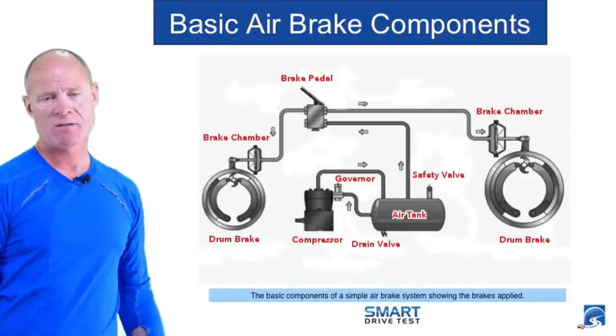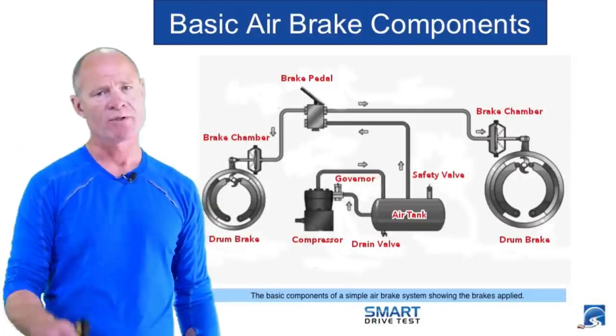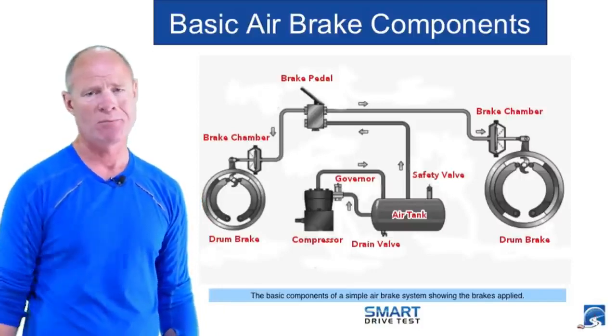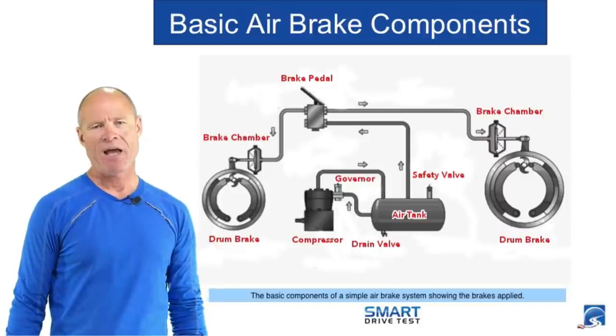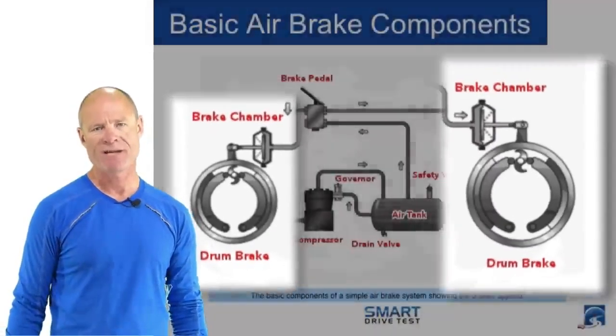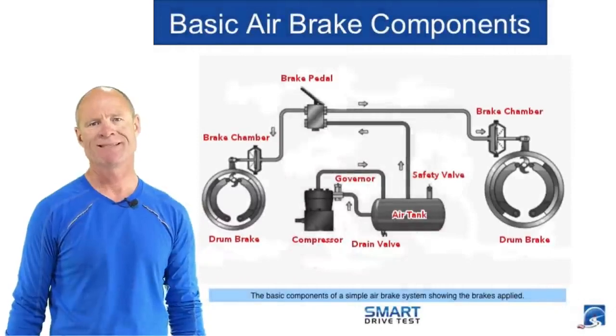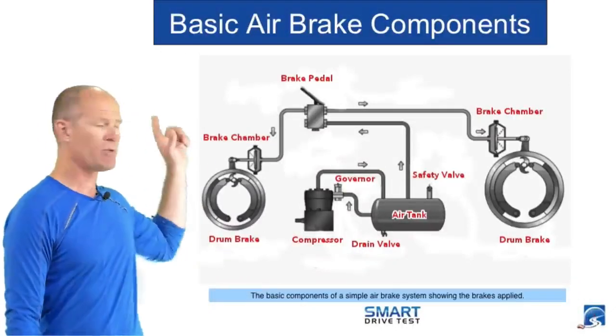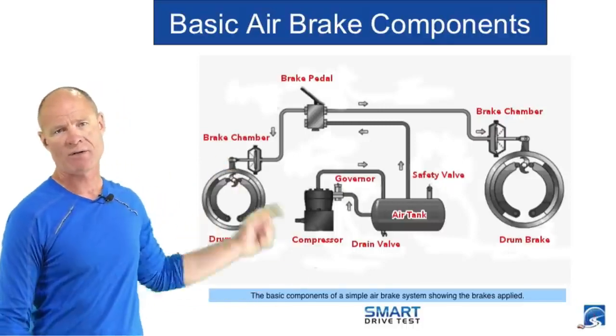The brake pedal can also be called the foot valve or the treadle valve, but for simplicity, we just call it the brake pedal. The brake pedal directs air out to the foundation brakes, and the foundation brakes consist of the brake chamber, the push rod, the slack adjuster, the S-cam, and the drum brakes. In this case, as you can see here in the diagram, these are drum brakes.